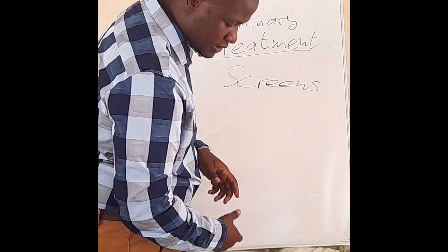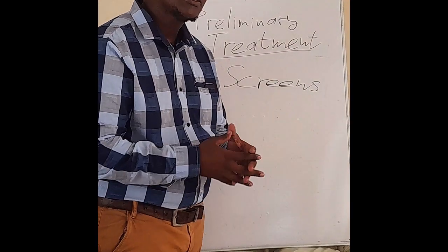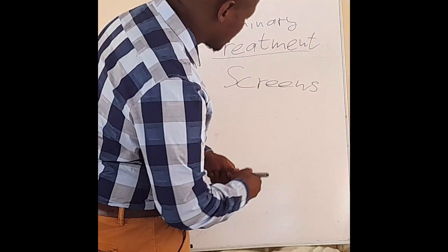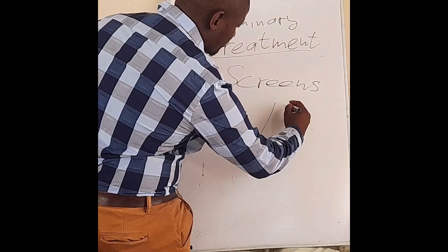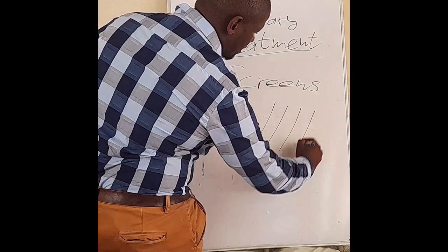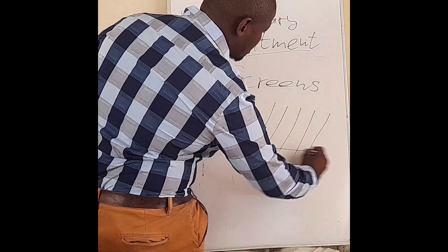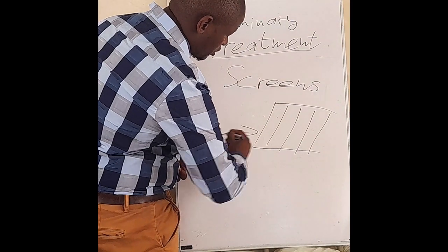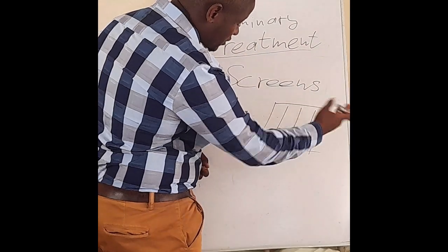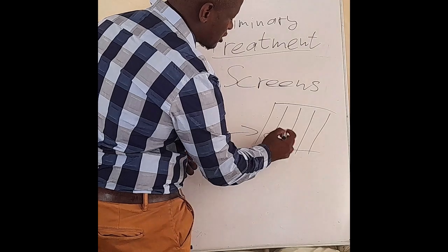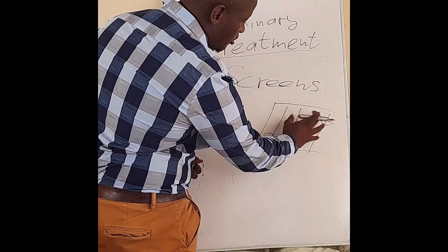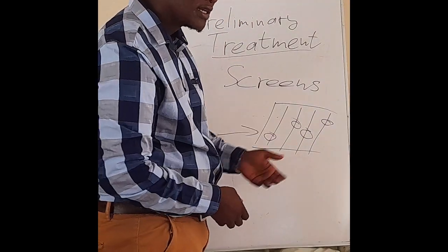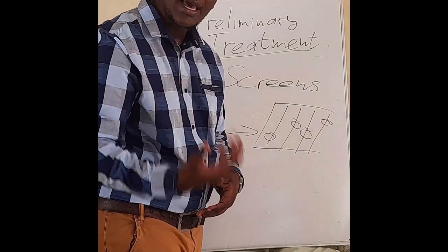As we had said, with screening we are removing solid particles, and the screens are normally diagonally shaped, and basically they look like forks. So water will normally go through these forks or screenings, and solid particles then will be held up under those screenings. There are different ones. There's the fixed bar screens, there's a mechanical one, there's also a hand one.